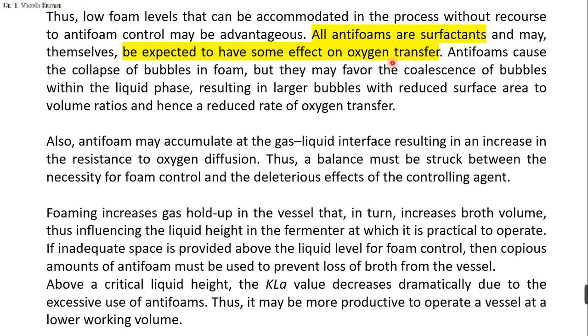The antifoam may accumulate at the gas-liquid interface, resulting in an increase in the resistance to oxygen diffusion. For example, if there is a bubble, there is an interface between the liquid and the air, and at the interface all the antifoam agents will be coated. So that will disturb the oxygen diffusion into the media. That may be the big problem with antifoam agents.